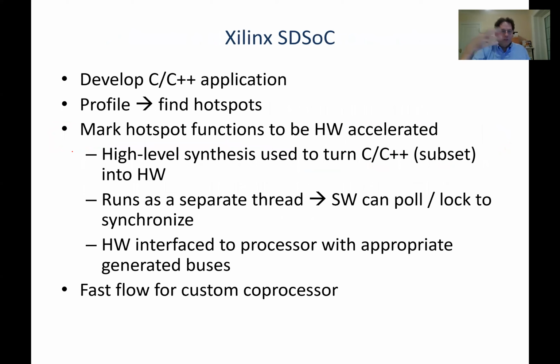Xilinx has a tool that goes a little farther, which is kind of interesting. So their SDSoC tool allows you to develop a C or C++ application. So you just write software, you compile it, you run it, you profile it, and that allows you to identify the hotspots in the software. And then you can mark the hotspot functions to be hardware accelerated. So you're working off one software code base. They invoke high-level synthesis to take that C or C++ and turn it into a hardware module.